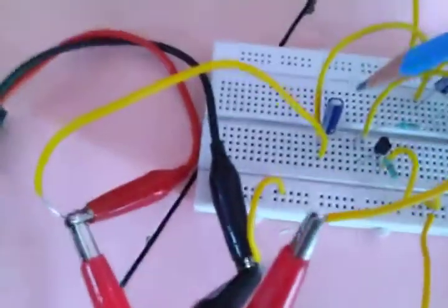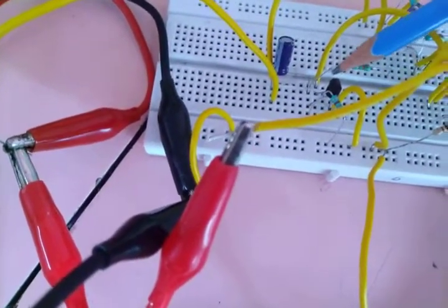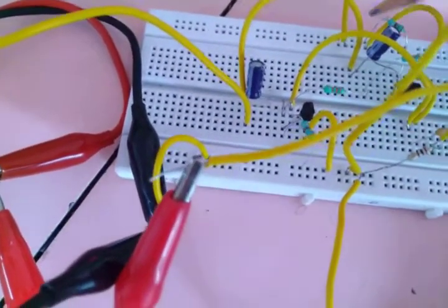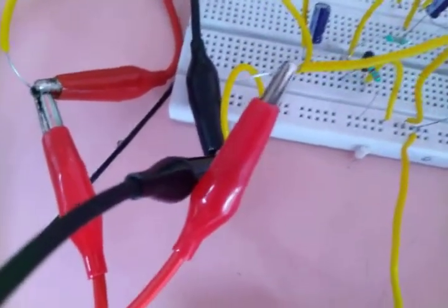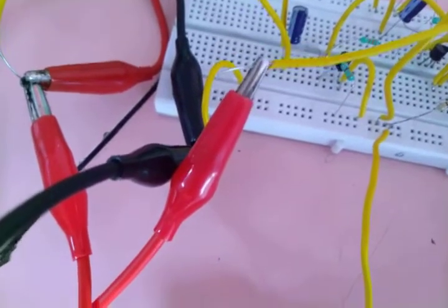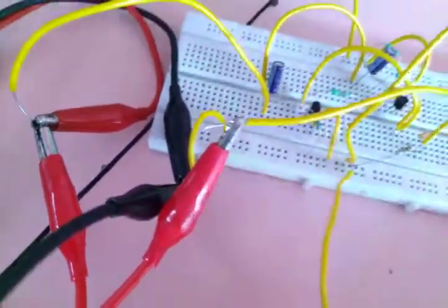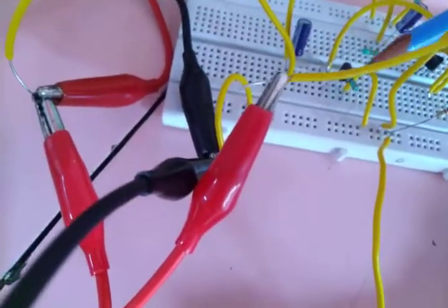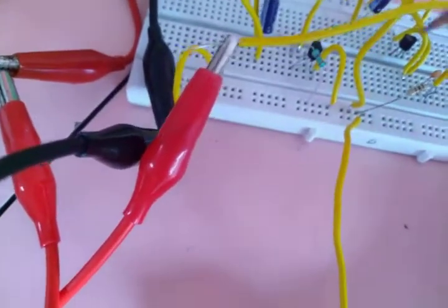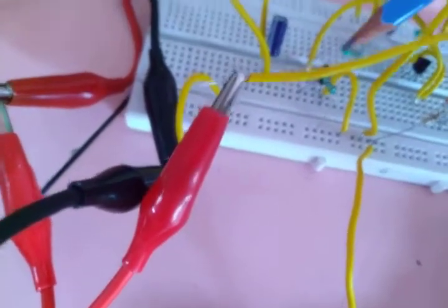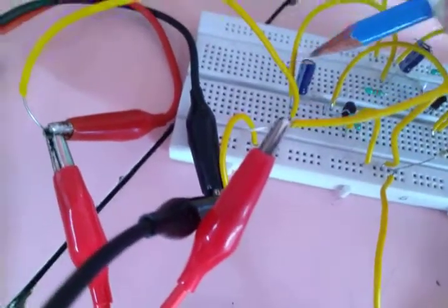And this is the coupling capacitor, the first coupling capacitor to the first transistor base, and second coupling capacitor for the second transistor, and these two are the resistors in between base 1 and base 2. So these two resistors are connected, and down here we see the collector resistance, and the collector terminal is grounded here, and base is connected to the input supply from the function generator.